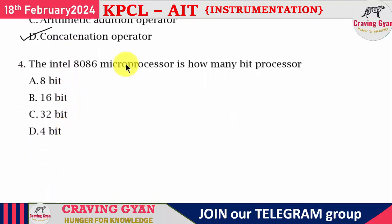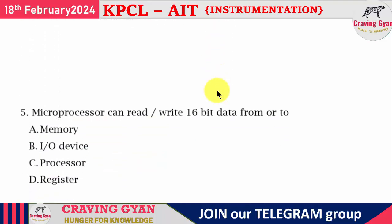Fourth question: the Intel 8086 microprocessor is how many bit processor, they are asking. Don't get confused and don't opt for something like 20 or some other option. It is a 16-bit processor. But if I am speaking with respect to address lines, it is 20-bit wide. And with respect to microprocessor 8085, it is an 8-bit processor. Even microcontroller 8051 is 8-bit. 8086 is a 16-bit processor.